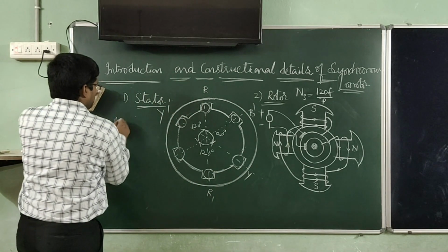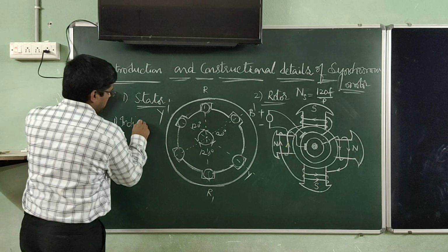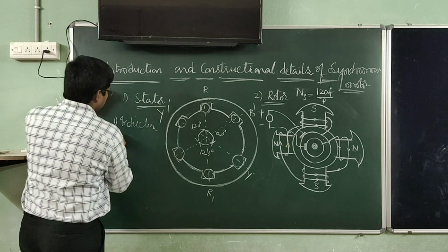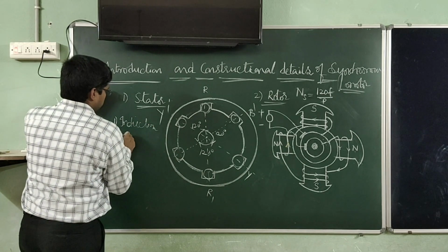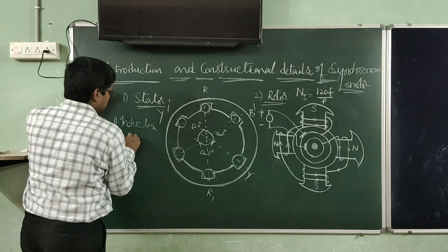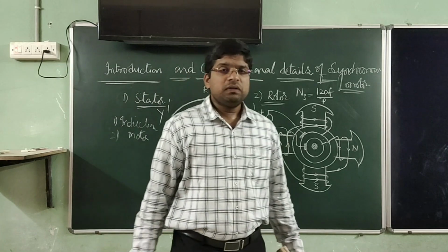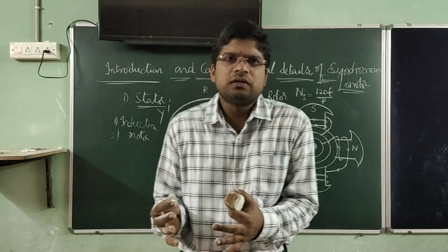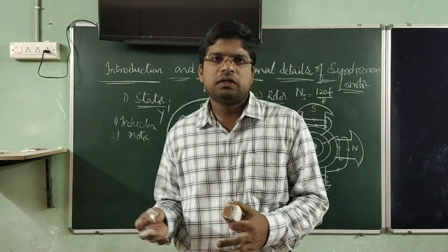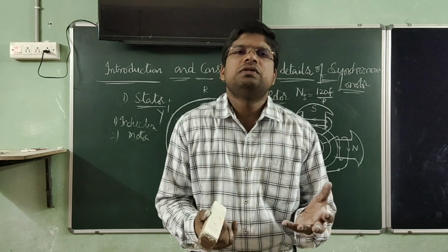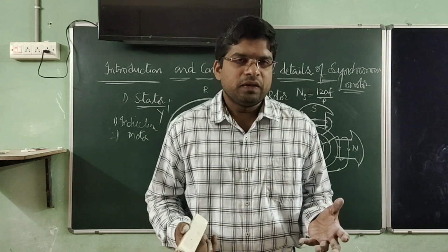And second way is by using a starting motor. By using an induction principle or by using a special motor to start the synchronous motor, we can make the synchronous machine self-started.